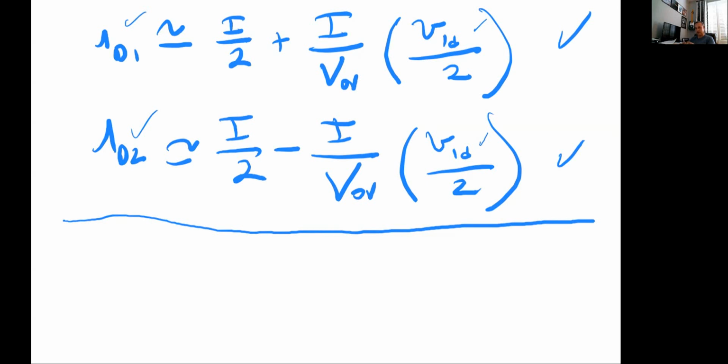And hopefully you can start appreciating and understanding why op amps at a macro level, from the outside, if you're using it, behave and operate the way that they do. And here is one part of that: we want a very small differential input voltage. If we have a very small differential input voltage, that's when we have linear relationships. So let's look at a couple of figures related to this.